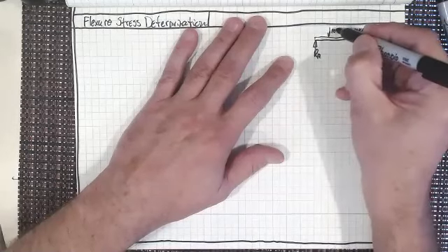So let's sum the moments about B equal to 0 this time. So R sub A is going to be clockwise around there. So it's going to be minus R sub A, I'll just put a bracket there. The minus is outside of the magnitude that I am determining right now, times 10 meters. And then I've got 10 kilonewtons times 8 meters. This one right here would be going clockwise.